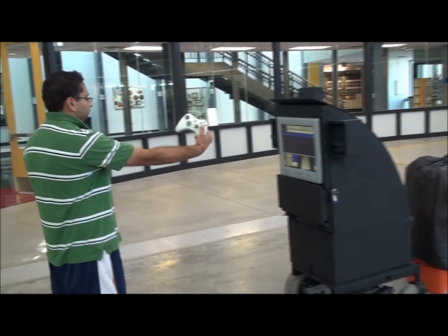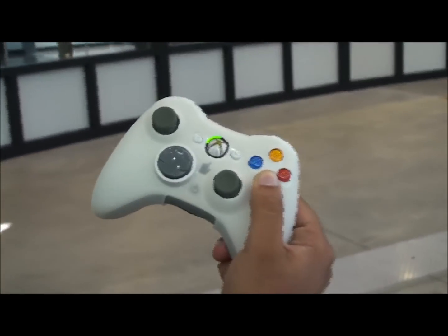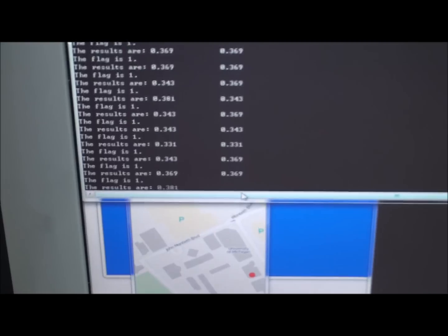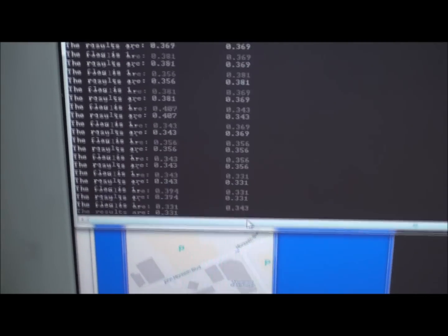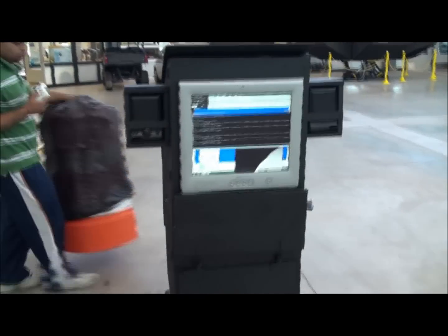This video demonstrates the flag being set for the sonar sensors. The flag is set when the object is within 1.2 meters of the robot. Once the object is moved out of the way, the sonar flag resets and the robot starts to move. When the object jumps back in within the defined 1.2 meter sonar sensor range, the flag is set and the motor stops.